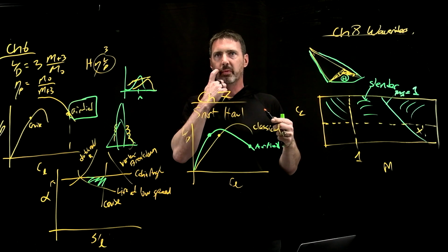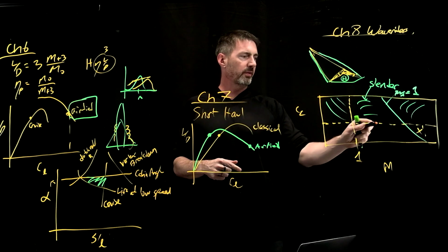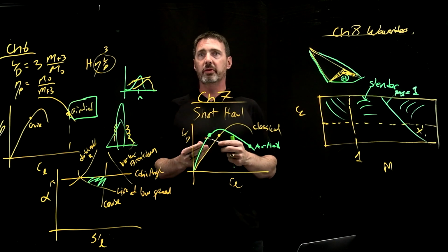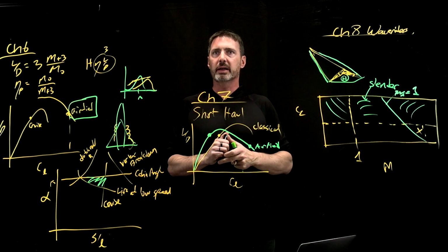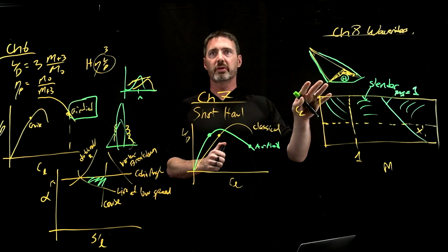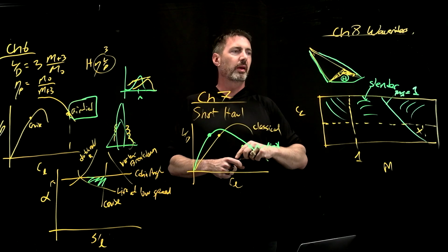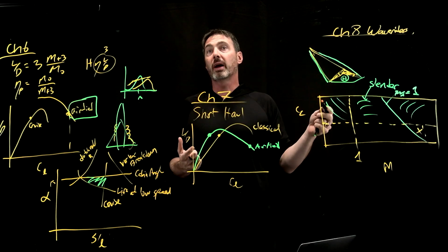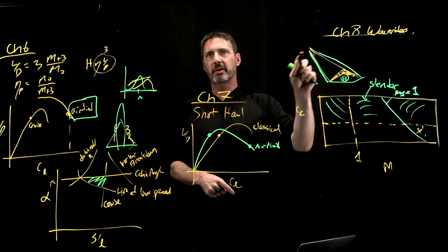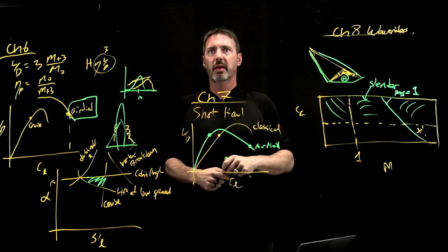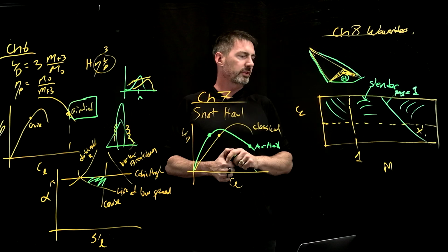So in fact, here at Venus, we looked into the waveriders for a little bit. We're no longer doing waverider because we're focusing on Mach 4, and that's a little bit too slow for waverider action. But back when we were looking at higher speeds as a boost glide vehicle, we certainly took a dive into the waveriders. And what I can tell you is volume is challenging, and because it gets thinner up front, your center of gravity gets challenging. It gets too far back. In fact, you almost end up having to put so much ballast up front that your payload becomes challenging. So certainly some interesting technologies.